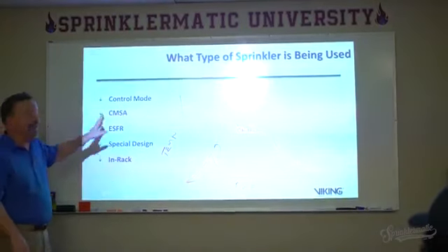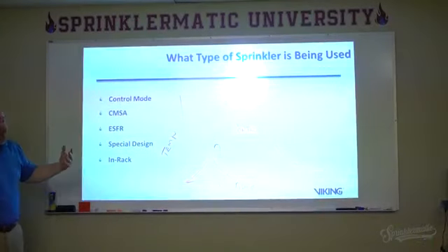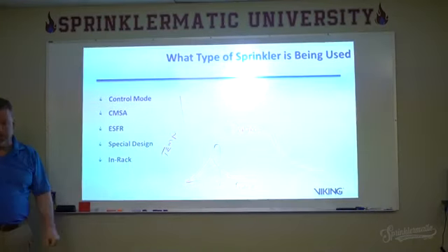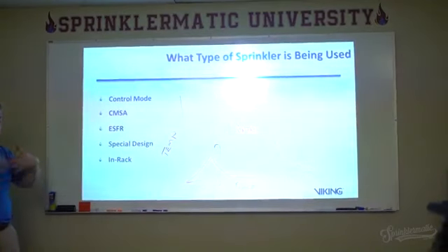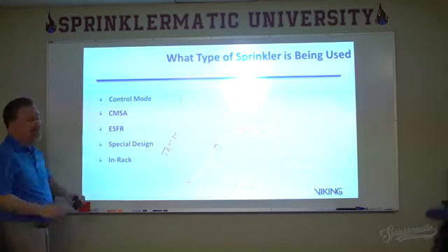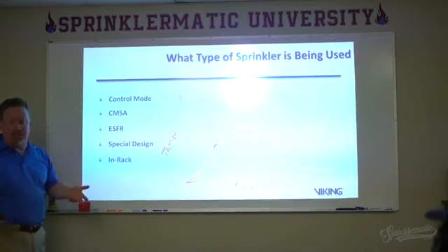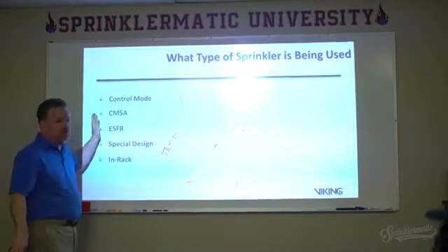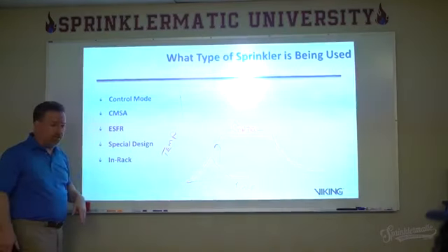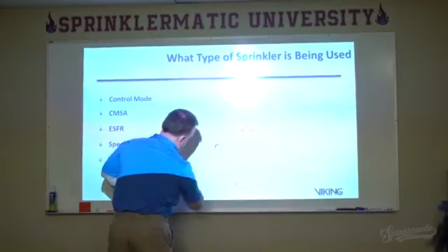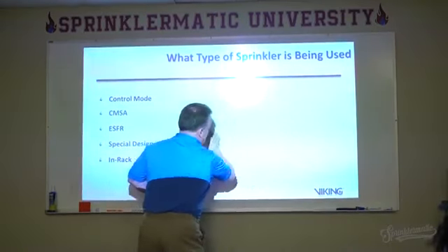Now, they can be used otherwise, but I don't want 100 gallons a minute coming out of a sprinkler in this room. I certainly wouldn't need it. It's over-designed. It's intended to protect high-challenge fires that normally occur in storage occupancies. That's what we've tested these for. That's what they're geared for.